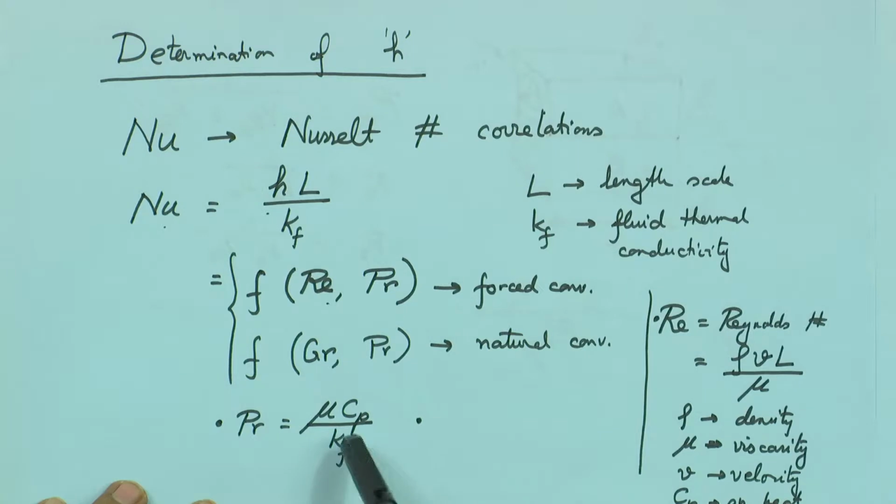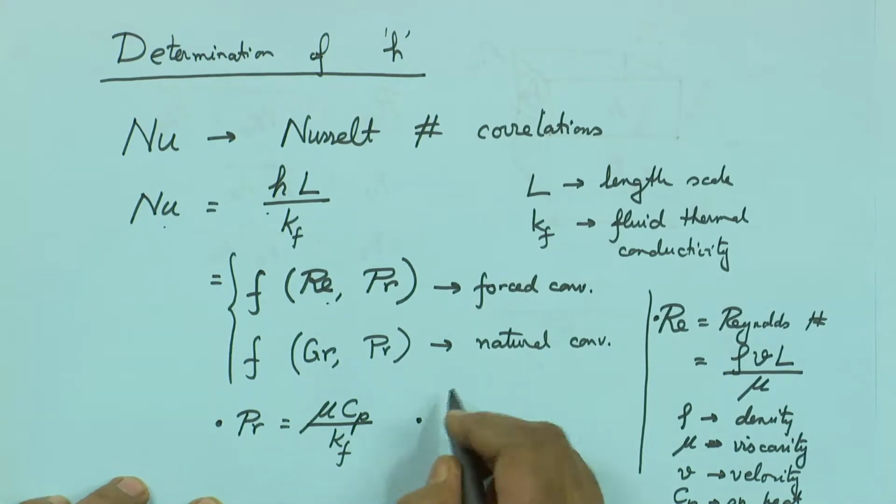Density, that can play in both ways. One is if it is a heavier fluid, it also helps because for a given volume there is larger mass, so it can move more heat, but it can also hurt you the other way. And then Prandtl number also, you see that higher the thermal conductivity and the viscosity. What else? Last one, which is Grashof number.